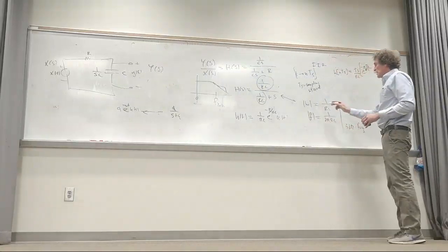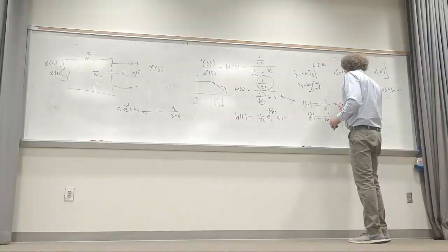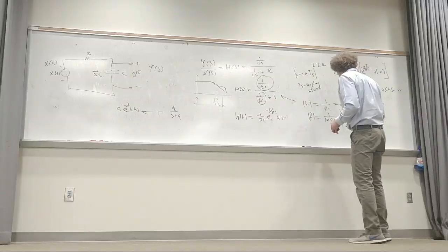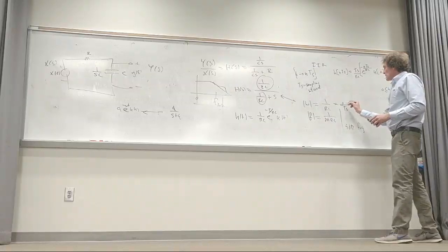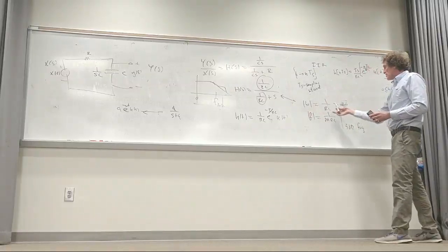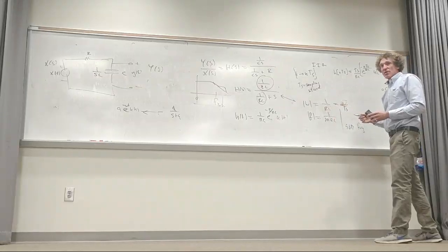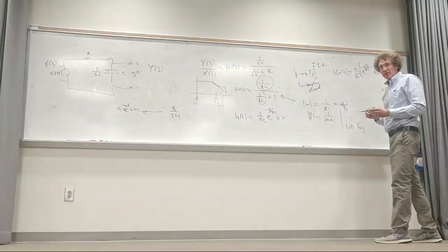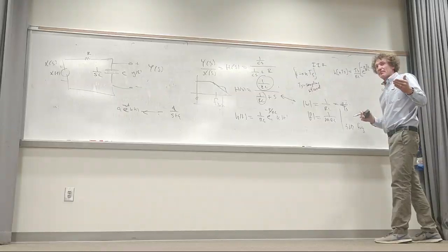However, when I look at this omega, that corresponds to capital omega divided by capital TS. So if you wanted to know where it was in the capital omega domain, you'd multiply that by TS, or you'd multiply TS times 1 over RC, and that would be the 3 dB frequency in the capital omega domain. Follow me in this class? Remember, this is sampled.